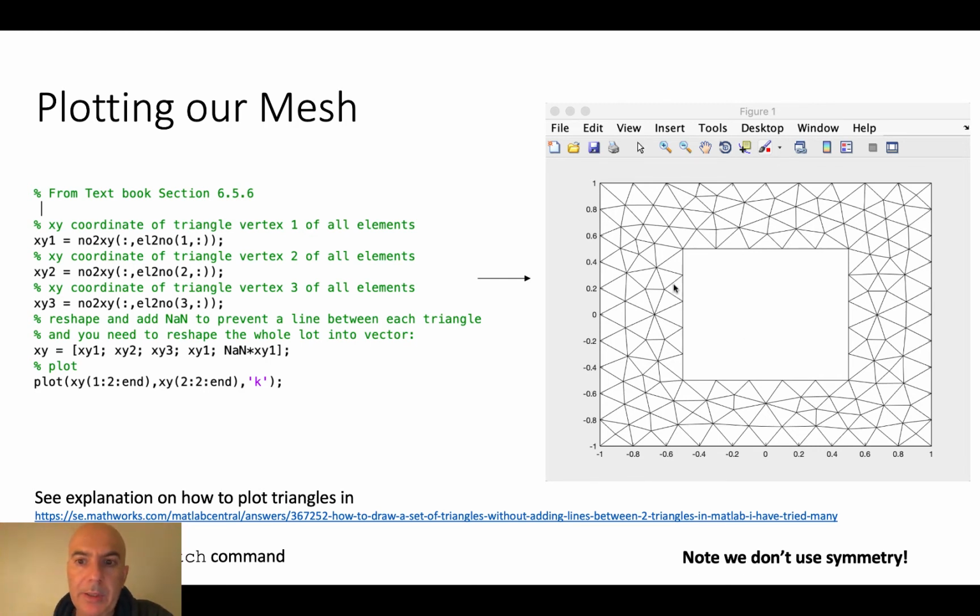One important difference is that for our second assignment, we only used one quarter of the domain, and then we applied normal boundary conditions on this axis here and this axis here. In this case, we provide a meshing of the whole domain, so we don't use this boundary condition and reduce the computation using the symmetry. So that's the first step. The very first practical aspect is basically to load the mesh, understanding how the mesh is formed, how many elements and how many nodes are present.